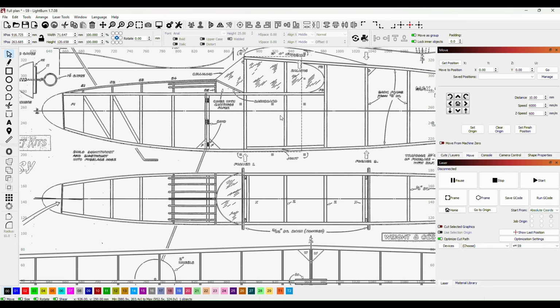And then all I'm going to do is bring it down and rotate it round, and then using the same method as shown earlier, if I convert that to nodes, even though it won't show nodes because it's not converted to a pathway yet, if I hover over this line here, it will, and press A, it will level it up. So that is now level.